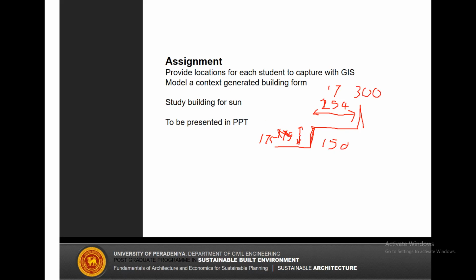And then the biggest mistake people do is you select the wrong material here. So if your material here is slippery, you have to have an anti-slip arrangement here. Not having that is the greatest problem. Usually if it is tiles, you have it's cement, sir. Factory, it's cement. Cement. Okay. Then it is compulsory. You have anti-slip staircase strips. You have to paste on this.